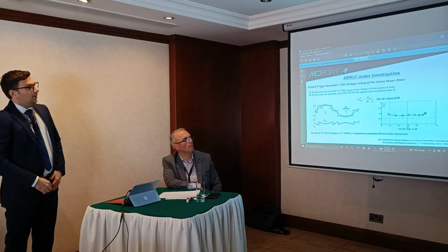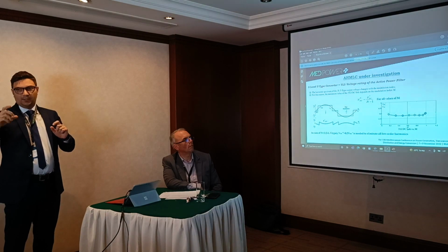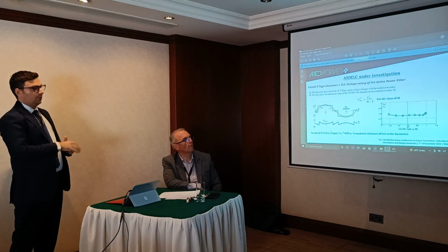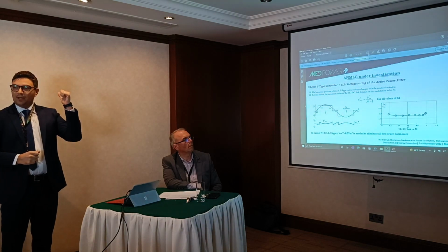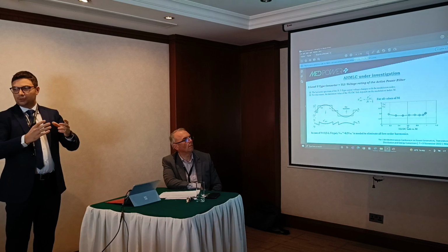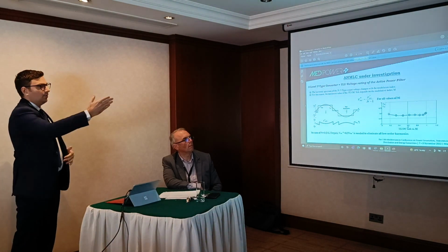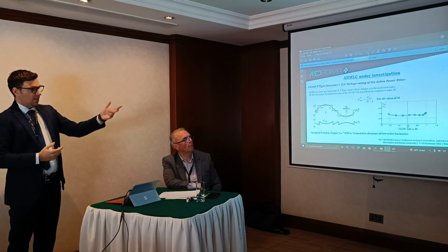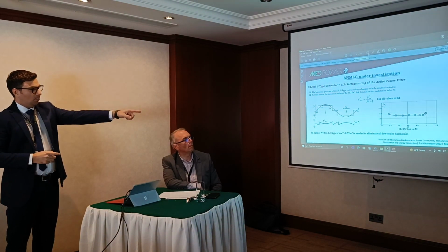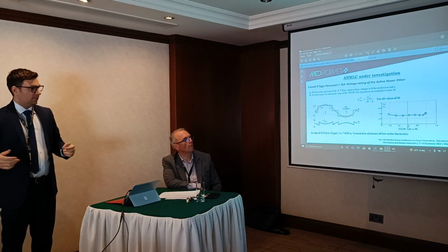But the value of the DC link of the two-level converter, or of the active power filter, depends on the modulation index of the main multilevel converter, because when we change the modulation index, the harmonic spectrum also changes. But we can see that in the case of n equal to 3, three levels in this case, we need a DC link of 0.5 VDC1 to eliminate all low order harmonics.